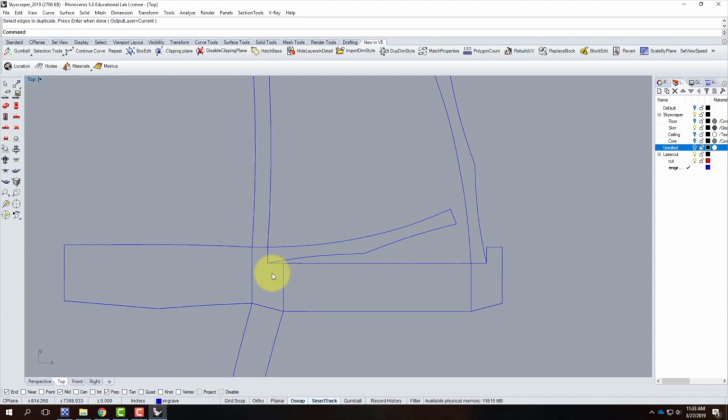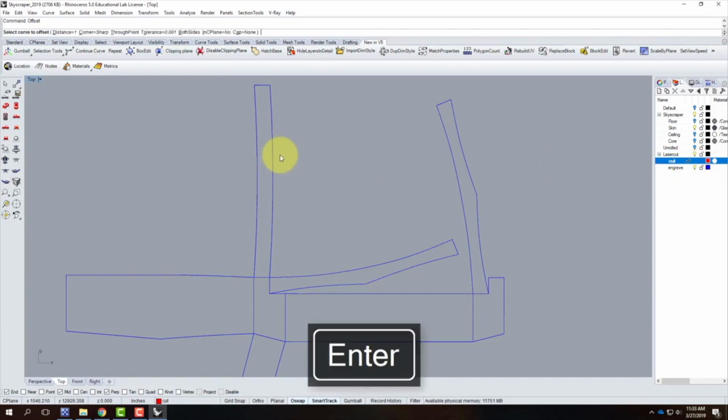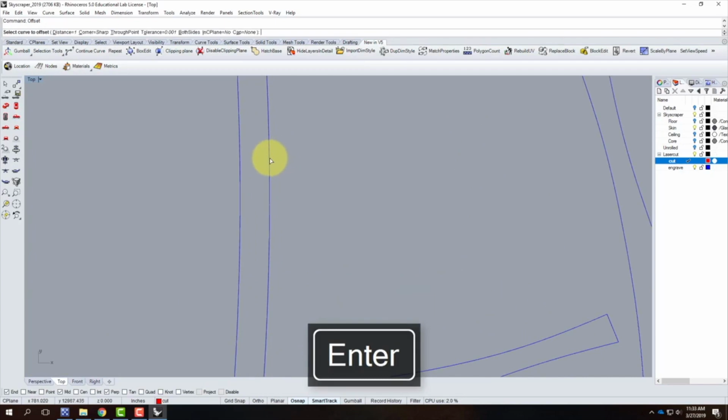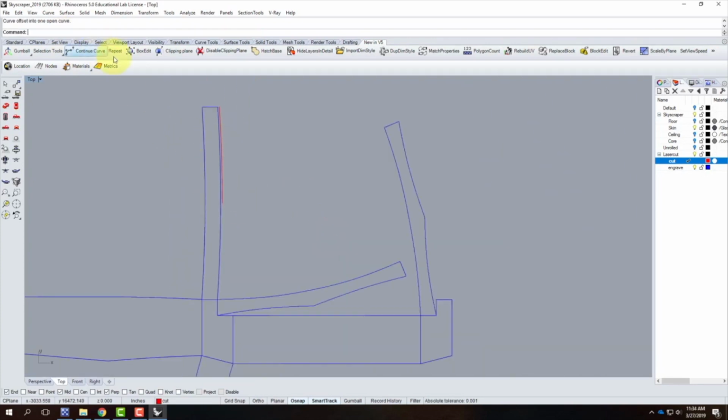but it's a lot easier to cut it out of a Bristol and just fold the tab and glue the tab. And so in this scenario, I'm going to offset these curves over a little bit to create those tabs. So I'll use the offset command, and I know that these ones are ultimately going to be cuts, so I'll go ahead and switch to my cut layer as my active layer. I'll do an offset, and the offset distance is just kind of an arbitrary value. We need to specify what it should be. I'll say that the distance is probably about like that for my tab. It doesn't really matter what the actual value is. Looks like I'm at about 60 feet or so, or 60 inches, sorry.